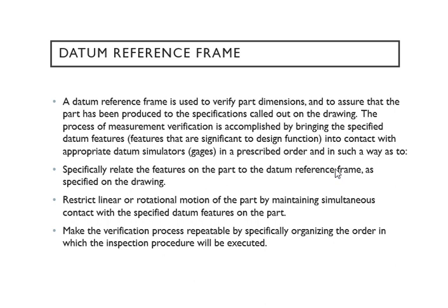And that's what we do in verification. So for outside features, you relate it as written in your drawing, and you go to the datum reference frame in your drawing to look at all the stuff you need to verify the dimension requirements. The rest of them are just reiterating the same thing.